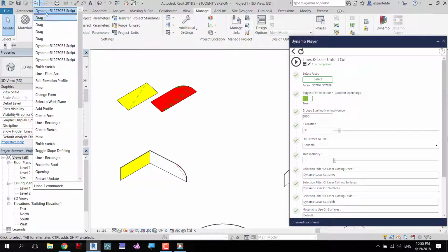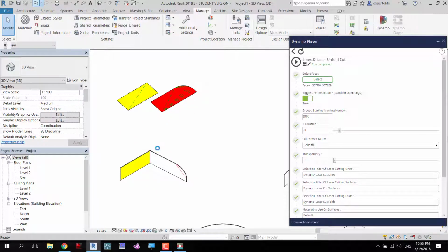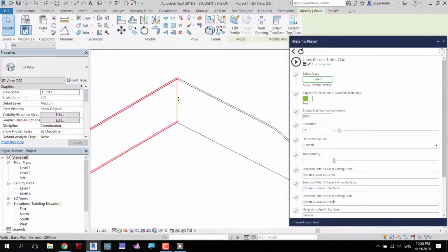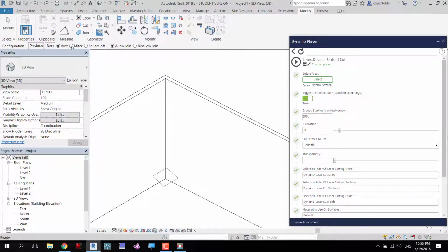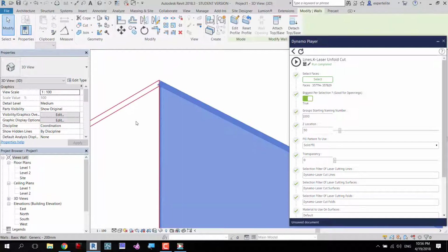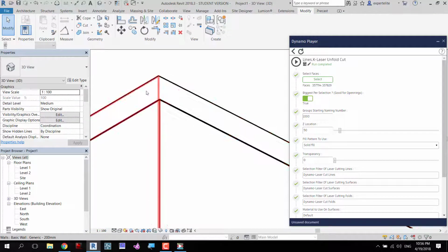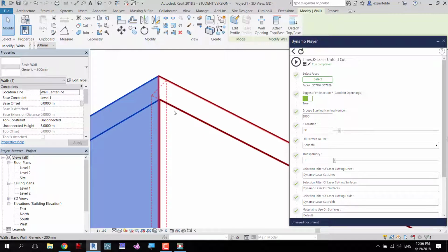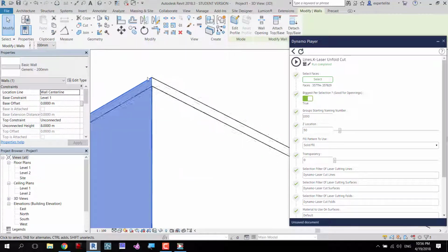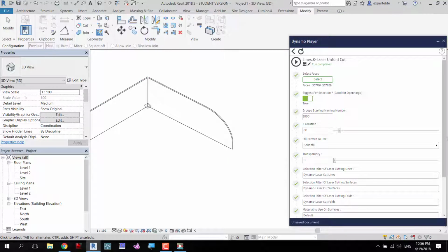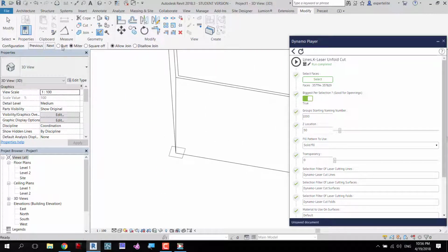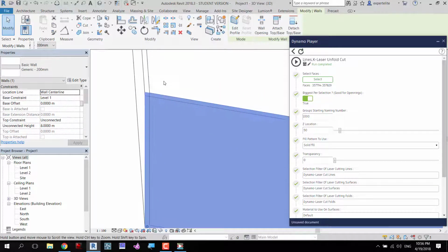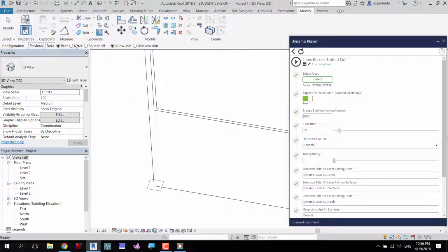This shouldn't happen. So in order to override this problem, you'll have to have your walls mitered. So wall joins and this, and miter them. Mitering them will actually make them equal in strength. So these faces are tangent to these faces. If it was not mitered, it's something like a butt joint. So the joining configuration is something different. I don't want it to be like this. I want it to be mitered.